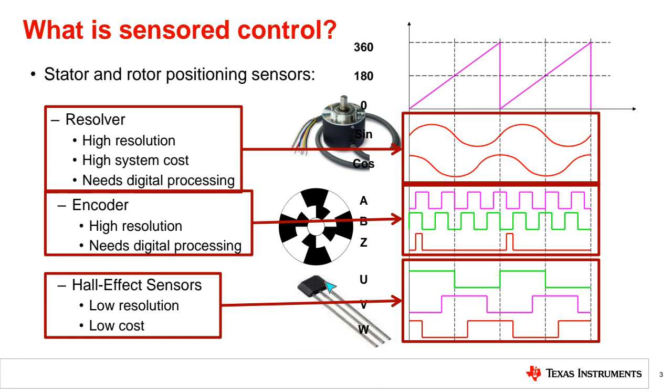But don't forget, every Hall sensor detects one phase. If you control brushless DC, you have three phases. Three phases means U, V, W, ground, and VCC, 5 cable. If you have a 5 cable for position, this is probably a Hall sensor.